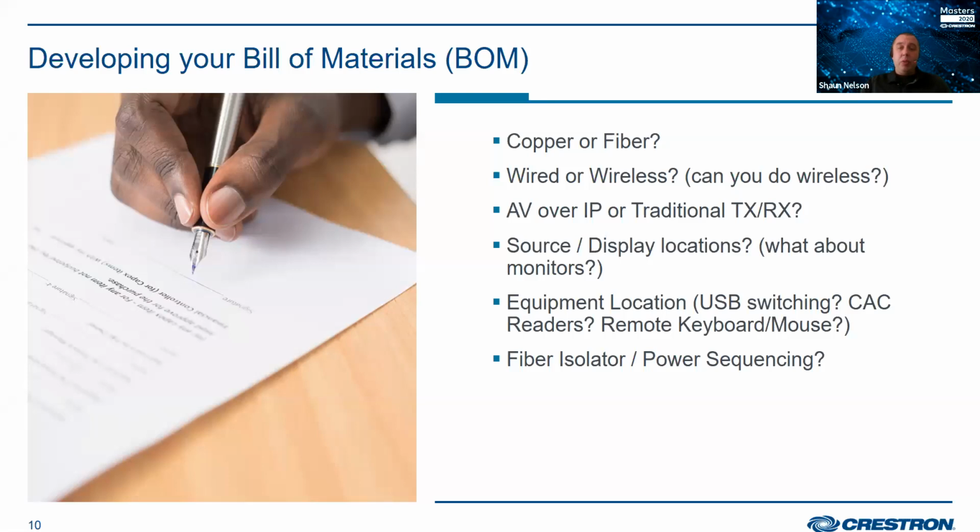But my question was, what about doing some sort of an optical isolator? You do have third parties that have fiber isolation, and really what it is, you're passing a fiber cable into this and it's then passed out on the other end to relay that information. When you close your contact, it shuts that fiber communication off, the equivalent of cutting a fiber cable in half.